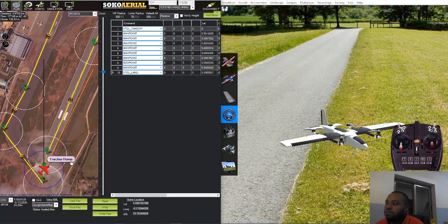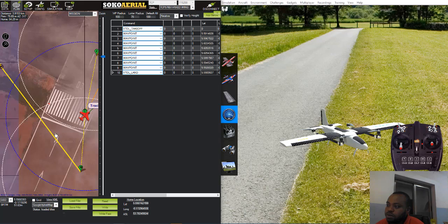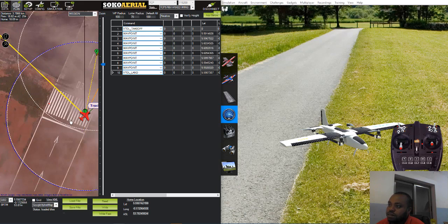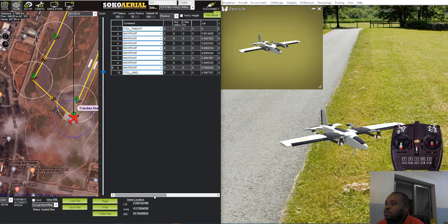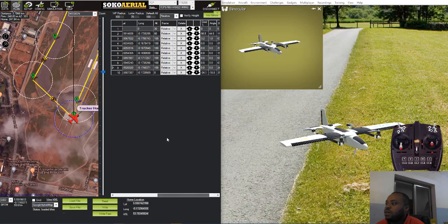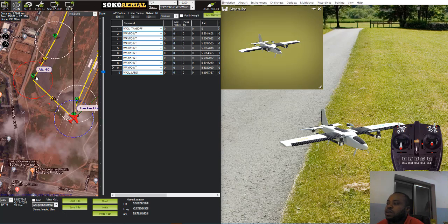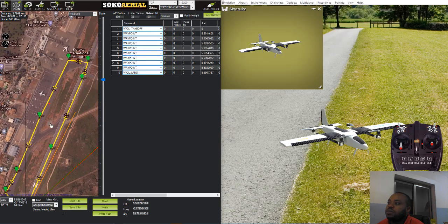Okay, now because I'm going to take off here and I want to return back, I need to make sure that my turn is exactly where I want to land. Okay, and then when I'm making this transition, I want it to also have a smooth landing, so I make a decent height drop to, let's say, 40 meters from waypoint 9, and then gradually it brings me to this waypoint. Right, that's beautiful.